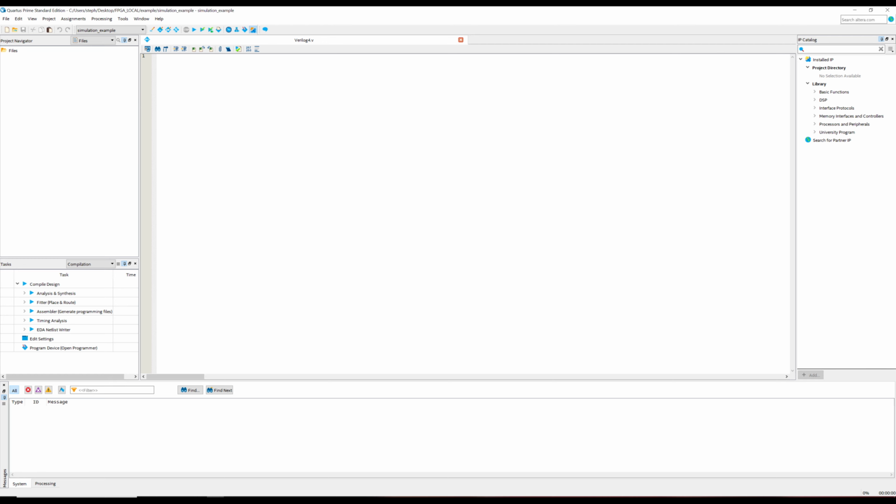So the code I've written here is one of the simplest modules you can write in Verilog. This is just a very simple 4-bit counter. And let's say we want to test the functionality of this module. So, one of the things we would want to do is just check that this is behaving as a counter and just check that the value of count is incrementing on the positive edge of clock.